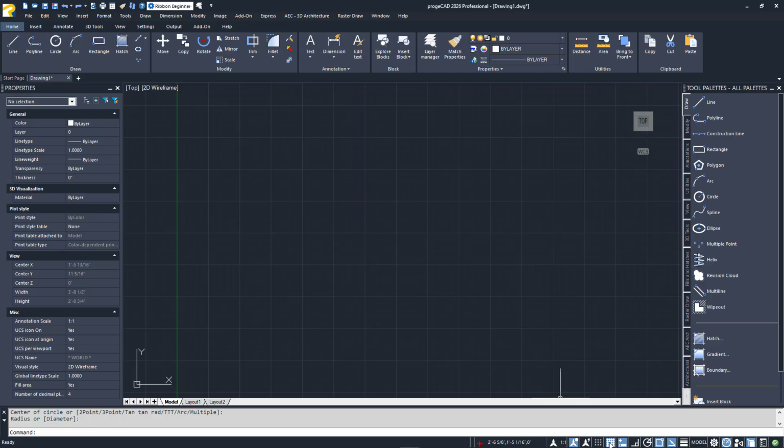First up is Grid. Mine is turned on. It displays as a light gray grid in model space. It looks a bit like graph paper. Without Snap enabled, it's really not useful, and many users, including myself, turn it off. However, if your drawing is schematic in nature, such as a wiring diagram, flowchart, or P&ID, Snap and Grid can become extremely useful. You can set up Snap and Grid into a configuration that works for your task.